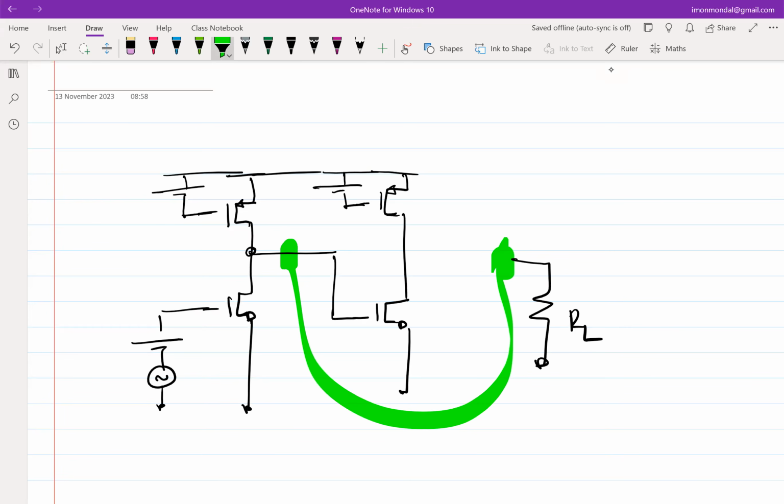So in certain cases, you don't have to drive a resistive load. For example, in this current structure, the first stage is driving the second stage, which is essentially a capacitive load. You see the CGS of the second stage. So it's not directly seeing RL, which essentially tells us that RL is not directly loading the first stage. That is why the second stage was there. Now, what I am essentially asking is, what limits the gain of the first stage?